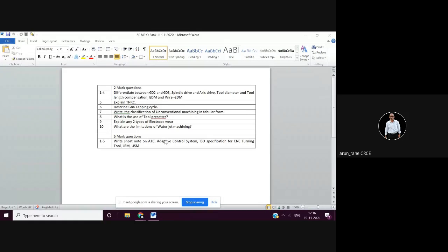Like if there is no material to be cut, it senses. No material cut, it senses. Right now the tool is cutting. All of a sudden, suppose there is a slot, that means there is no contact of any material with the tool. That means there is no force acting on the tool. Correct. So there are force measurement transducers. So it senses now there is no force.